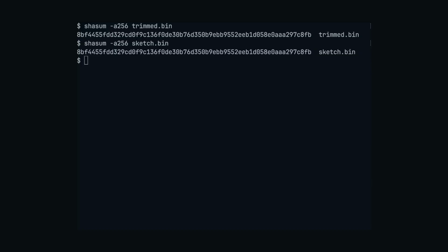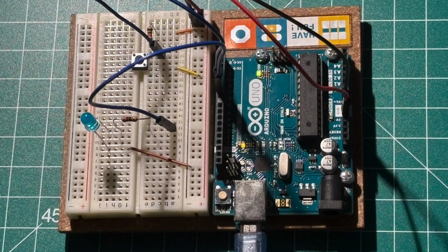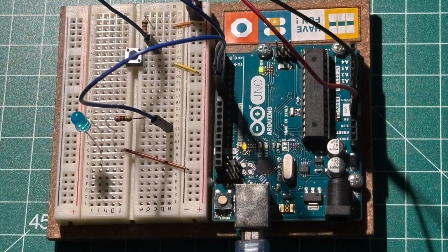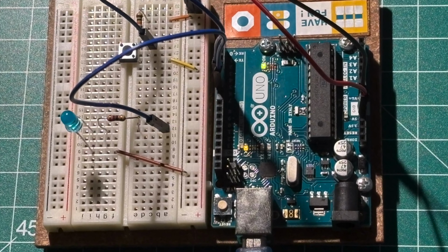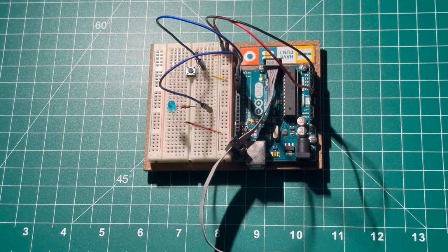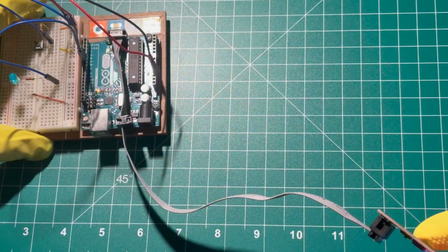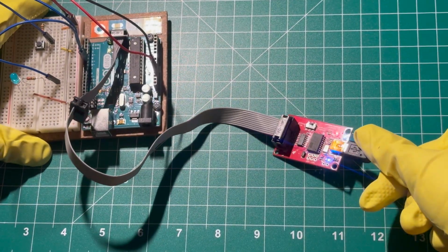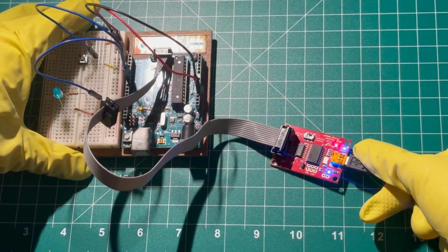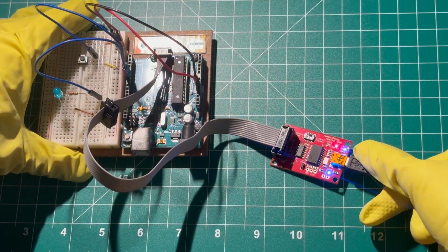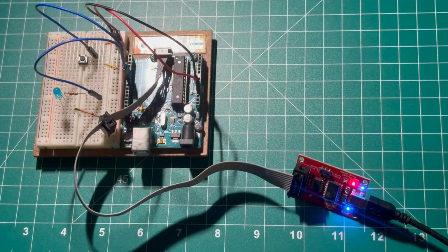further in the future. As good stewards of security research, the next question we should be asking ourselves is, how do we prevent this attack? Well, we can check the fuse pins to see if read protection is enabled. For that, we will need to read the ICSP pins, which are connected to the memory where the bootloader configuration fuses are held. We indirectly extracted this information earlier when reading off the full firmware from memory.